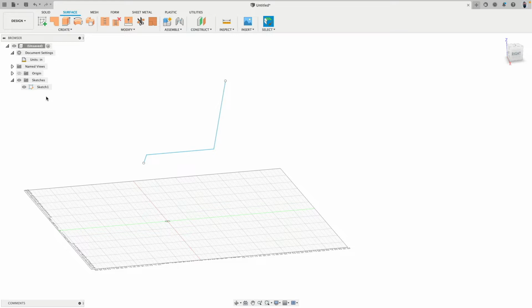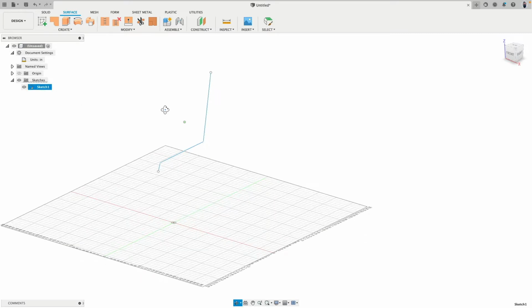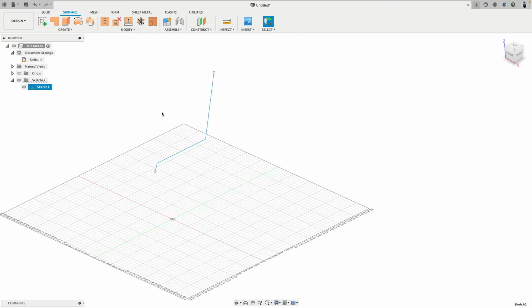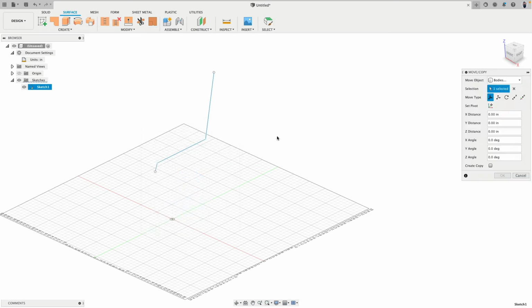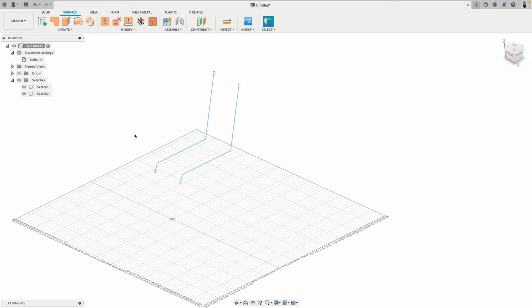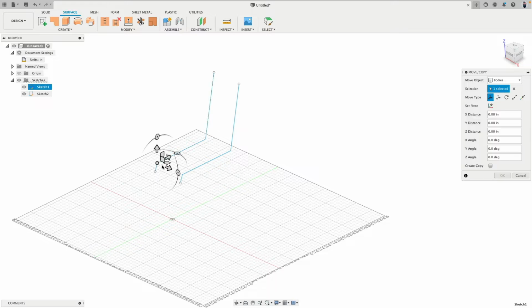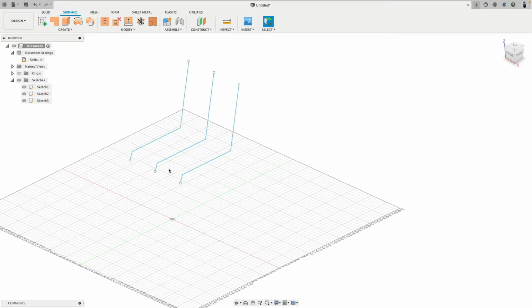Now, when we sit where our hip is, we want the chair a little bit go down, and to the left and the right, we want the backrest to kind of like go around us. So we can't really do much with a single sketch here. So let's do this. We go to modify, make a copy, and this sketch, make a copy 8 inches to the right, and then right click, repeat, and this copy 8 inches minus to the left.